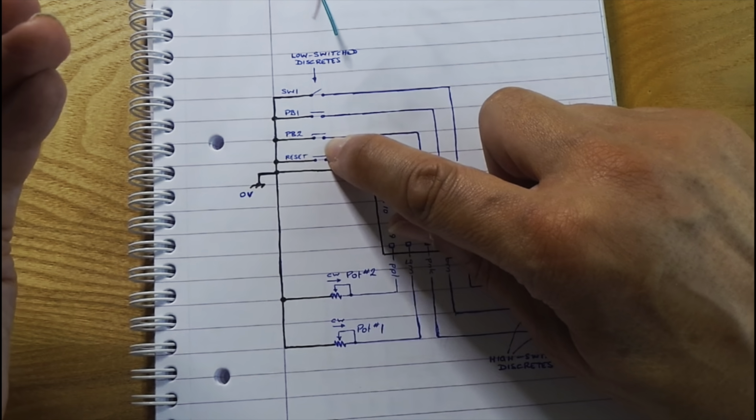Pin number 1 is an orange wire, which is at the bottom row and the right hand pin, and this is a 12 volt connection, which is a 12 volt output from the dash module number 3, and you probably won't use this. The main reason for this is to enable us to test the unit easily on our test bench, because this puts out a 12 volt signal, so that enables us to drive switches which represent high switched inputs.